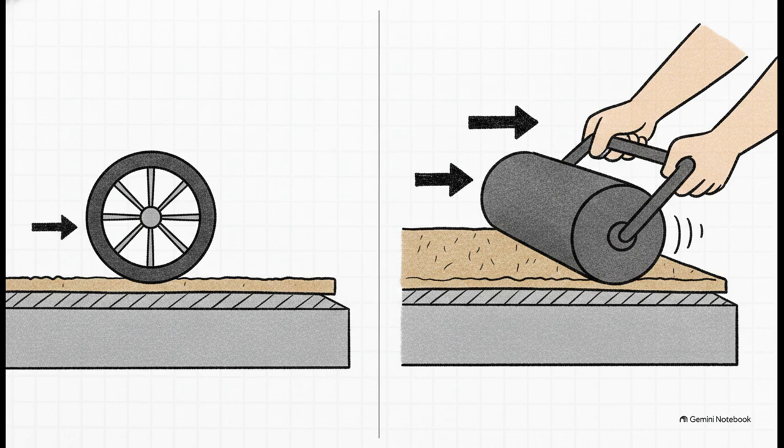Since there's zero padding involved, the carpet keeps a very low profile. That makes it the absolute ultimate choice for heavy rolling traffic, ramp areas, and places needing wheelchair accessibility. It virtually eliminates seam peaking and buckling altogether. But to guarantee that the adhesive fully transfers into the carpet backing, you absolutely have to roll it in both directions with a heavy 75 to 100-pound roller right after it's placed. No skipping leg day on this one.